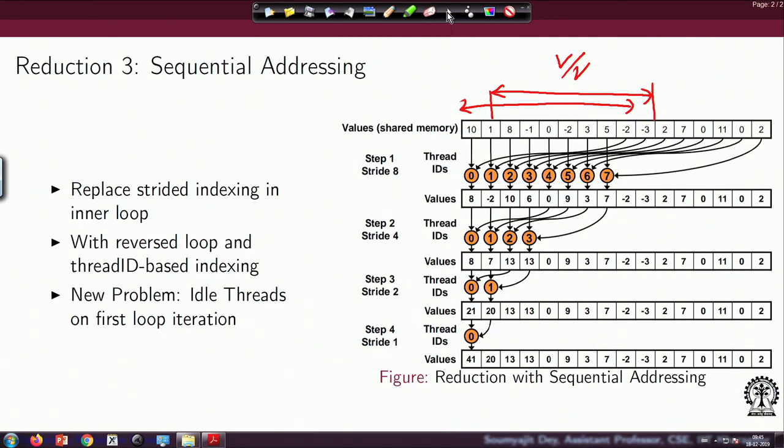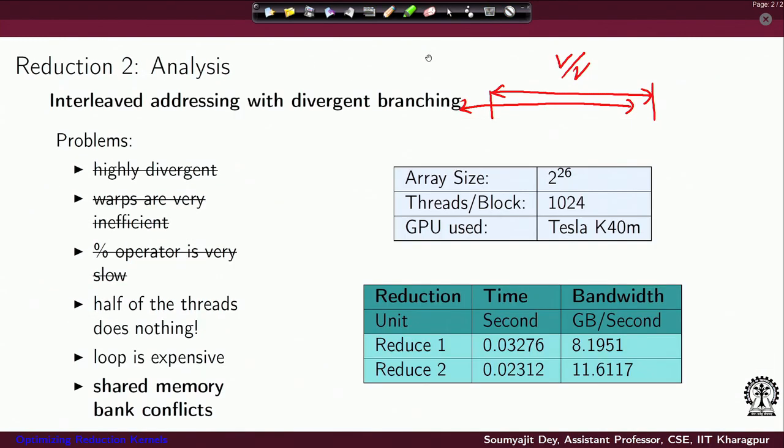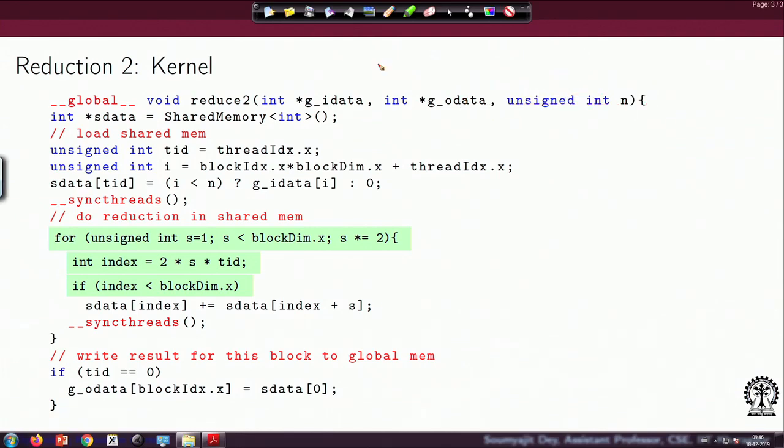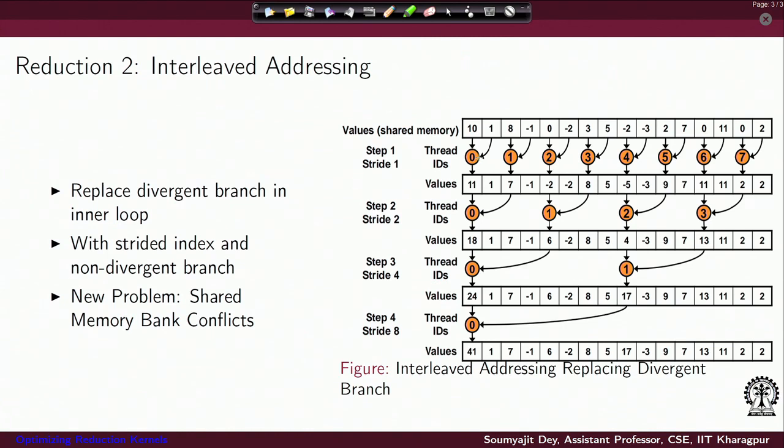So, just for clarity, let me repeat what happened in the earlier scenario. Here, all the threads with consecutive IDs from the same warp, no divergence, but while loading operand 1, they were accessing locations with 1 hop, and that would effectively lead to a two-way bank conflict, which would occur for both of the loads individually.